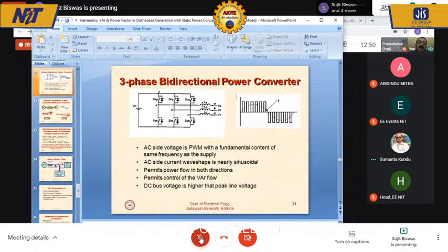here, and this can be thought of as the synchronous reactance of a synchronous machine. So at this end, you have a fundamental voltage created through the inverter with a series reactance, and then you should be able to synchronize it to the grid the same way as we synchronize an alternator onto the grid. So it's a synthetic alternator. It's not a real physical rotating alternator. You use the same logic to connect it.